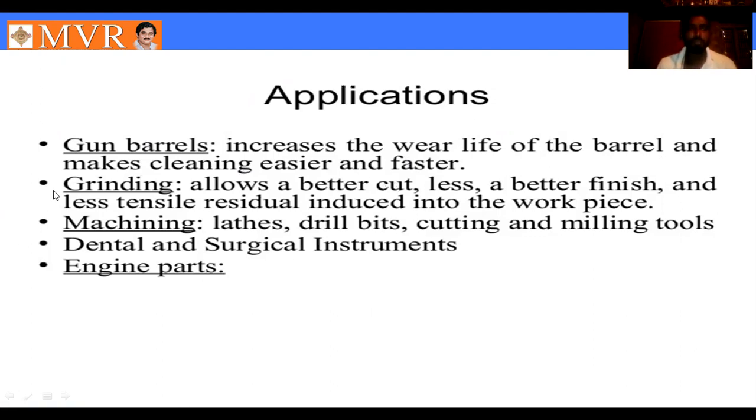In the grinding process also, we can use the cryogenic heat treatment procedure. It allows a better cut, a better finish, and less residual stress induced into the workpieces. So that is one of the grinding applications.